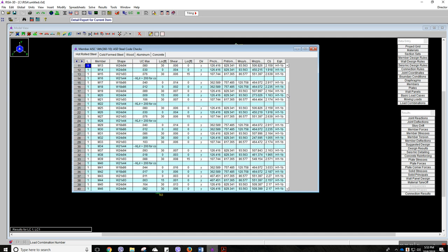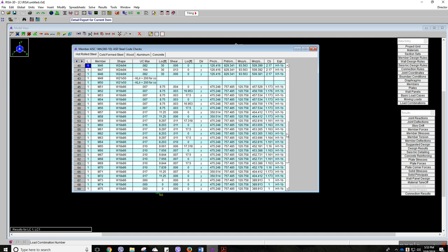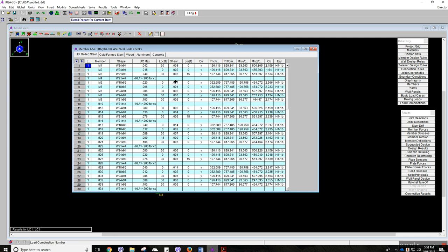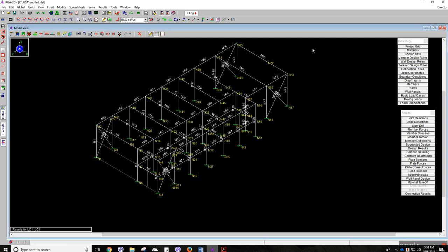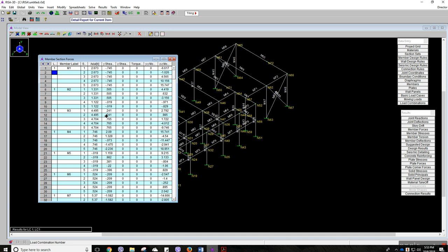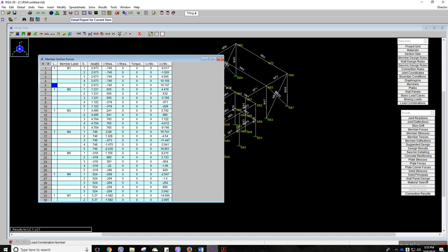This gives you all the shapes and the location of shear force, location and direction, and all the values that we have here: moment, shear force, and Cb value from the S1 equation. And one more thing you can see is the force on each member from the member force equation. These are all the axial force and shear force directions, and the moment in the y direction you have here for the different members.